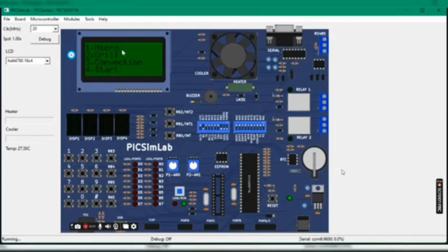Micro mode, grill mode, convention mode and start mode, we have seen earlier why we have to use them. So we are going to see the execution part in this output here. I'm going to press key 1 for the micro mode, and it has a power of 900 watts. I'm going to set the timer as per my cooking requirements, say 45 seconds and 2 minutes. Okay, let's enter. As you can see, the timer is started and the fan is running.